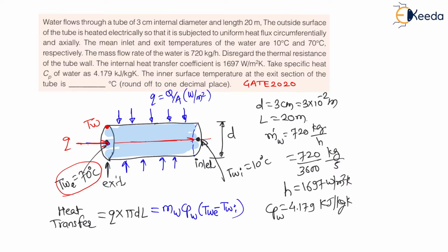And my dear students, can I say the heat transfer rate for steady state along the circumferential direction is the same? Now, between the first layer, here I will draw with red color, for the first layer of the circumferential direction, there will be a conduction, right? And the conduction is Q into pi dl area, right?